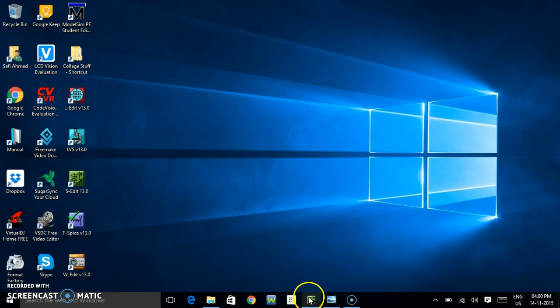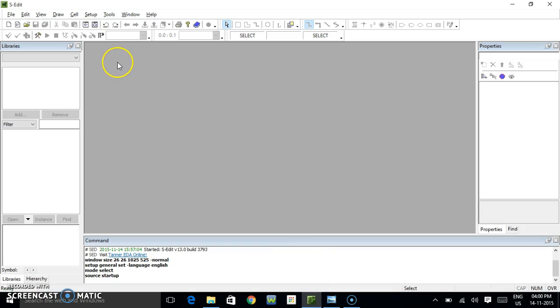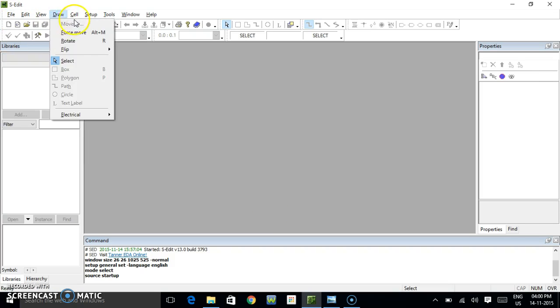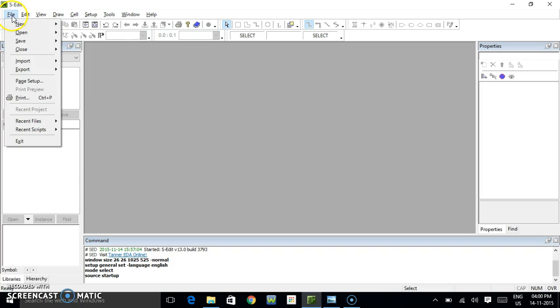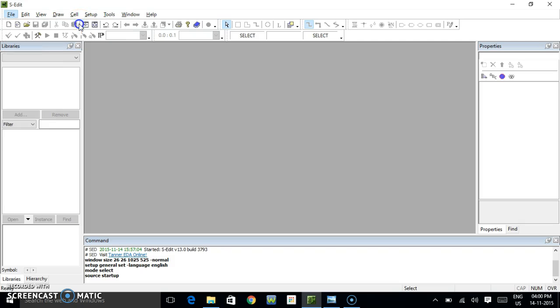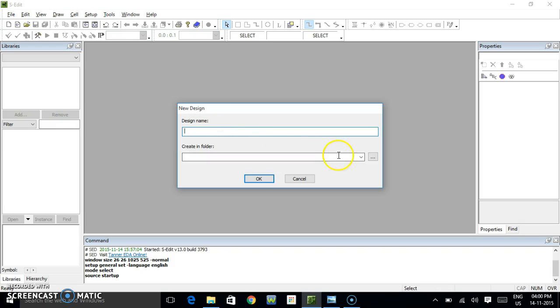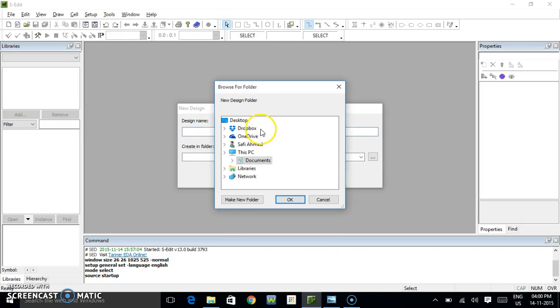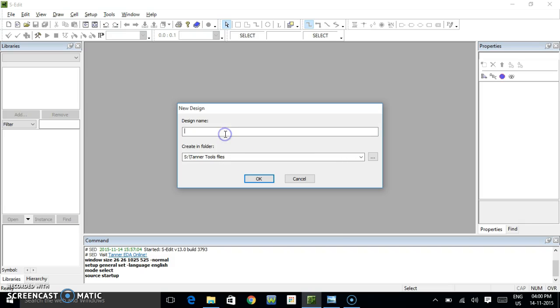and you will see how we go through the process. So let's open the S-Edit, and I think I won't be speaking for much time because you can see how I proceed through the video. I will only speak when some explanation is needed. So we start with the design name and we give the location where we need to create the folder. I'm selecting the Tanner tools folder which is present. I'll press OK, and I'll name the design decoder.